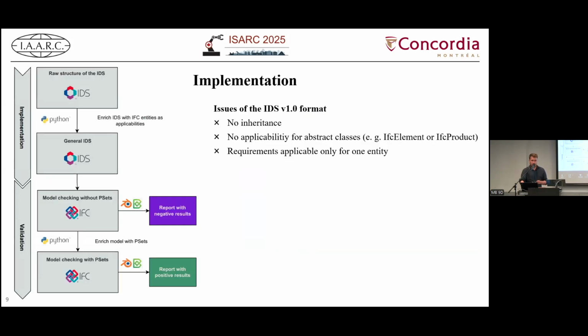In the implementation, we found a couple of issues with the current IDS format. There's no inheritance for the IFC classes, and it's not possible to have applicabilities for abstract IFC classes, for example IFC element or IFC product, to cover all possible IFC entities. It's also not possible for requirements to apply to more than one entity.